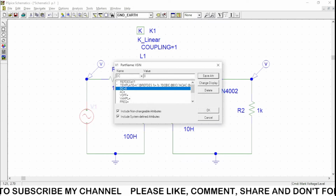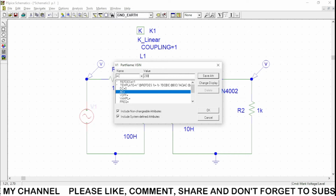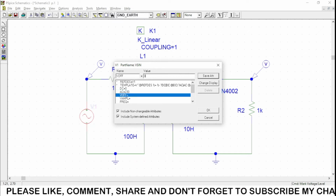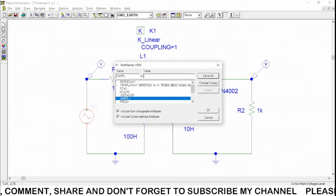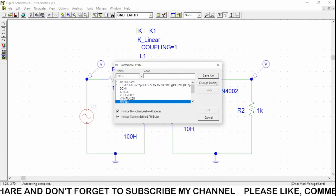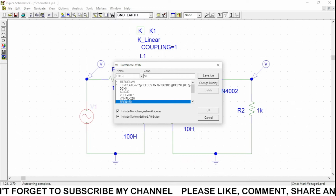Save attribute. AC, we need AC to be 230 volt. Offset be very small like 0.00001. V amplitude, VAC, these both are the same, 230 volts suppose. Frequency is 50 hertz, so it will take 50 hertz automatically.